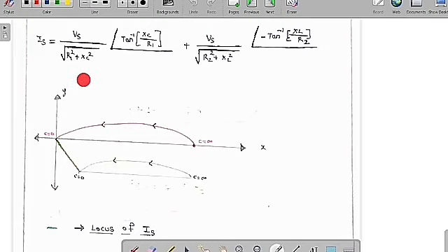But when you substitute C is equal to 0, what is going to happen? Because XC is equal to 1 by omega C, XC will become infinity. So Is by infinity is again 0. And similarly here, infinity by anything gives 90 degrees, so plus 90 degrees. So finally we are going to get plus 90 degrees.